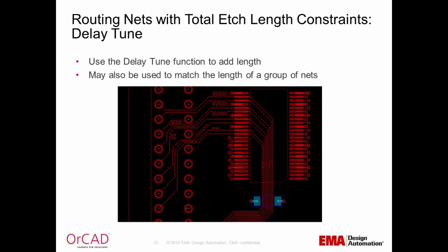Last, we'll talk about design reuse with placement replication. Placement replication is available through the placement application mode in OrCAD PCB Designer Professional or above. It allows you to save off component placement, related routing, localized copper pours, and reference designator placement of a particular circuit in a layout. The saved module may be reused within the same design if there are multiple identical channels, or in another design that contains the same circuit.